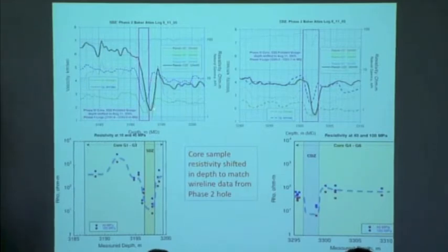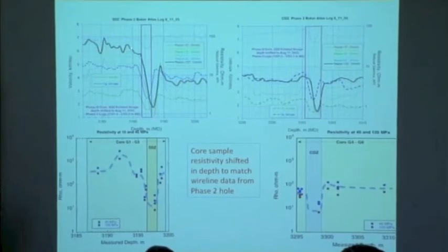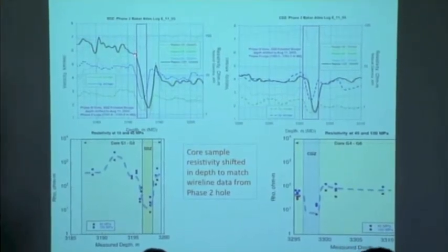The solid black curve here is the 10-foot resistivity log. This is measuring from transducers 10 feet apart in the borehole. And we see, again, this high resistivity coming into the SDZ, and then a massive drop in resistivity and recovering on the northeast side in the damage zone. And again, around the CDZ, another drop, essentially mapping the high clay content actively deforming zones.